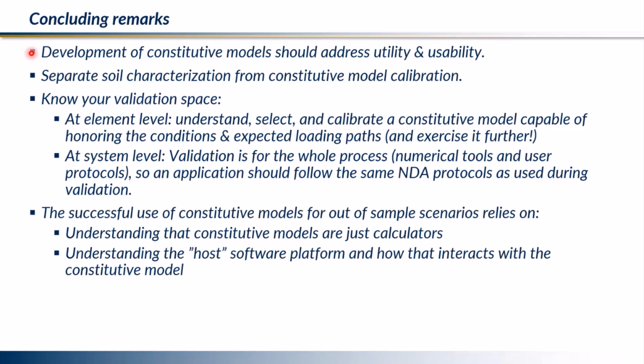Development of constitutive models needs to address utility and usability. We did that with the input parameters and the generalized calibration against what we know from the field. It's always a good idea to separate soil characterization from soil calibration. And then understanding the validation space, the loading paths that you expect, how your model will respond to those, what is going to get activated, and go into that loop of checking the element, going to the system and back. And then being able to successfully use such constitutive models.